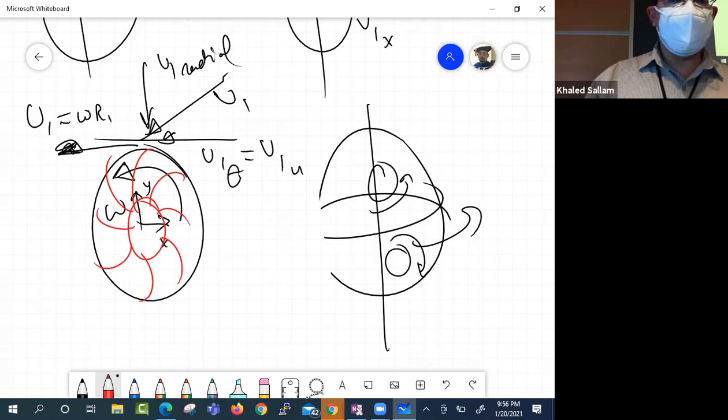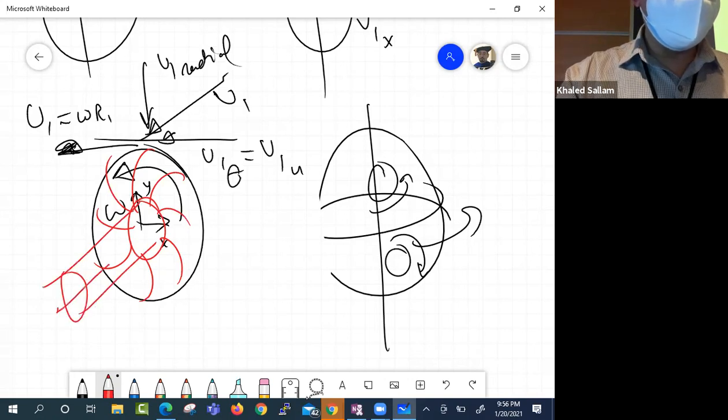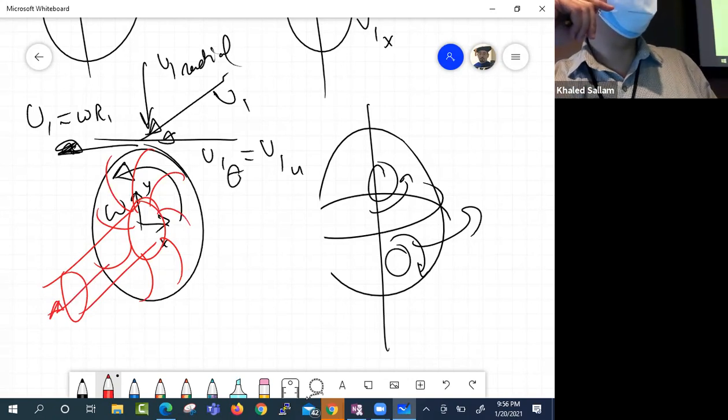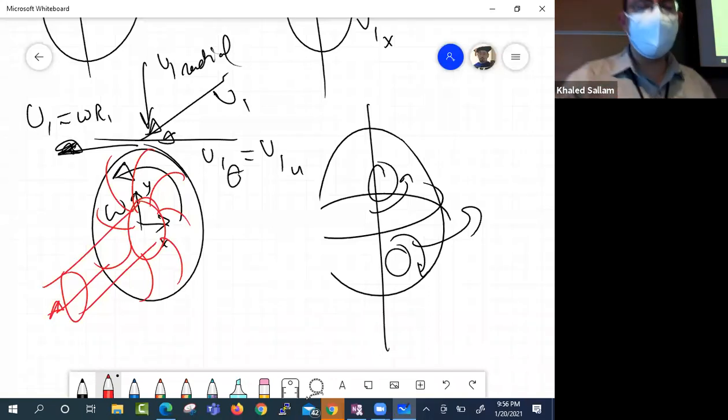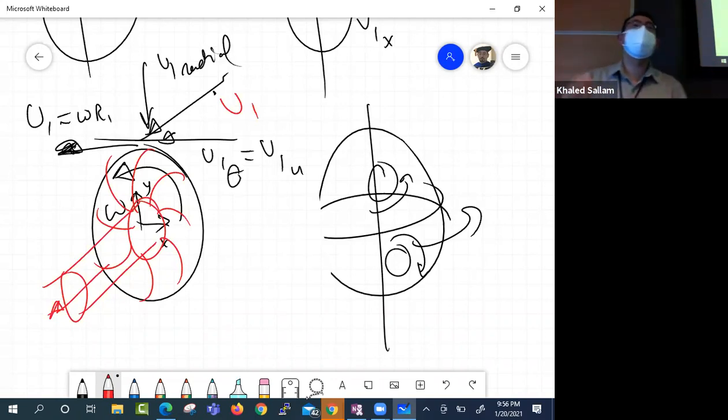Okay, and so once the flow comes and hits those plates, you can see it's coming with a twist. So it will end up spinning the plate, right? And then it would leave from the middle pipe here in the middle. We give it a lot of twist initially, so it's coming with big V1, big V1 theta. It comes with huge twist. And if it managed to leave with a little bit of a twist, did we lose our money or is that okay? We lost our money. We should consume all of the angular momentum that it came with, right?